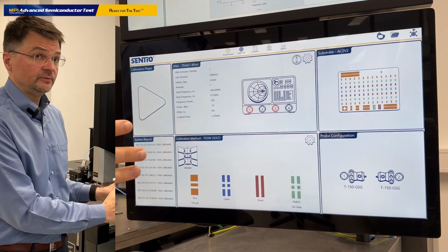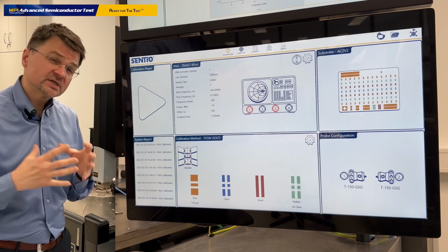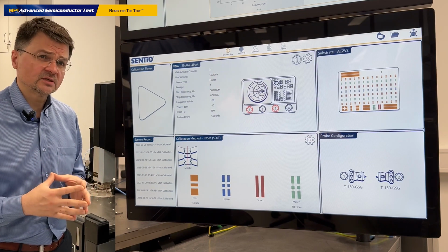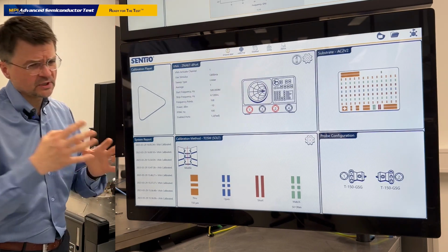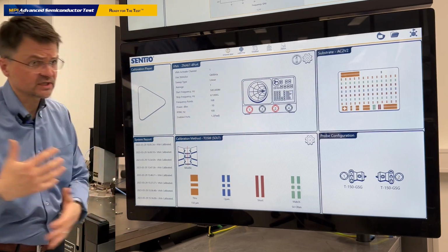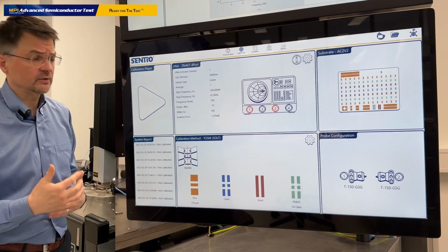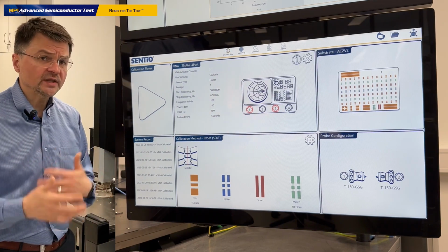So, single window operation of Calibria and Sentio when we need to calibrate the system. The calibration is a relatively complex task. You need to be focused on your probes, verify the contact, set the parameters of your calibration standards, define the sweep of the network analyzer, and verify the calibration accuracy, and all of it needs to be executed one after another.